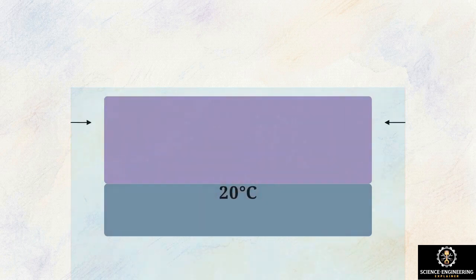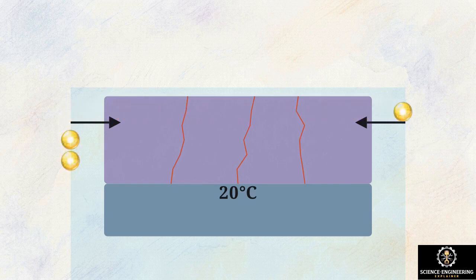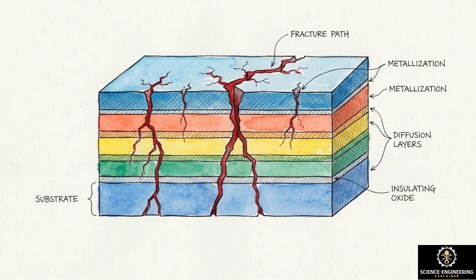Cooling the wafer to room temperature causes tensile stress, tearing the crystal structure and spawning threading dislocations that propagate vertically through the active layers. These physical defects act as non-radiative recombination centers. If a photon or an electron-hole pair encounters one of these dislocations, the energy is absorbed and neutralized, destroying the material's optical gain. To address this, engineers insert dislocation filter layers, alternating strained superlattices between the silicon and the active region. The strain in these layers forces the vertical dislocations to bend sideways and annihilate one another. While filter layers reduce the defect density, they do not eliminate it.